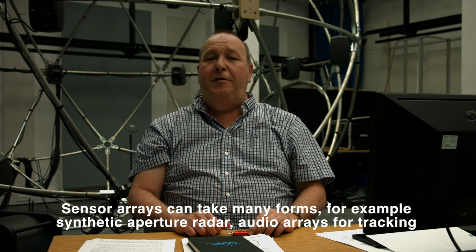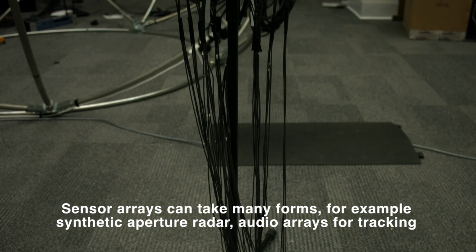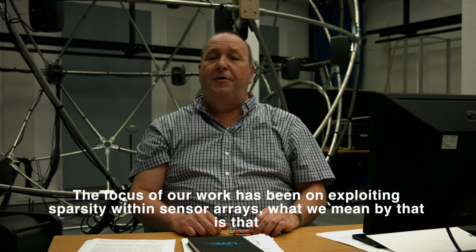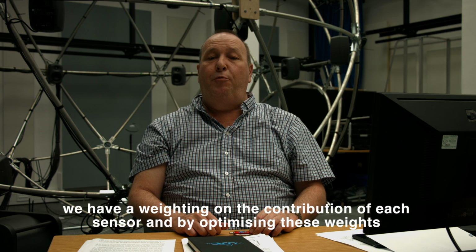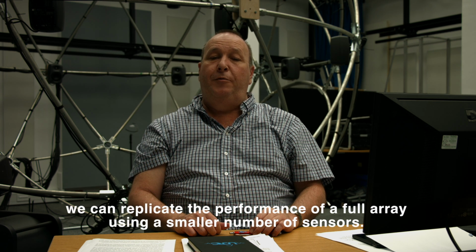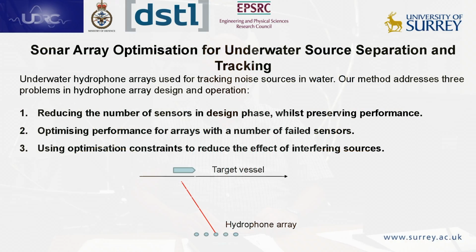Sensor arrays can take many forms, for example synthetic aperture radars, audio arrays for tracking speakers, or in our case, hydrophone arrays for tracking underwater noise sources. The focus of our work has been on exploiting sparsity within sensor arrays. What we mean by that is we have a weighting on the contribution of each sensor, and by optimizing these weights, we can replicate the performance of a full array, but using a smaller number of sensors.